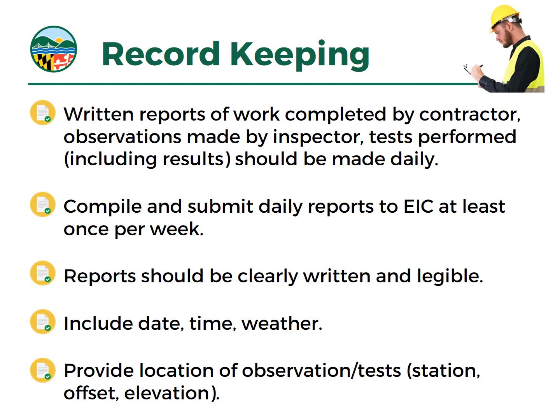Weather factors can be a huge impact in construction, whether it's hot or cold weather and how it impacts concrete curing, or whether it's really dry or really wet and how that might impact soil moisture conditioning. It's important to know. Why did we get all those failed tests because of excess moisture content? Well, it had been raining that day and 2 days before, and the contractor hadn't taken any steps to protect the subgrade. So that's important information.